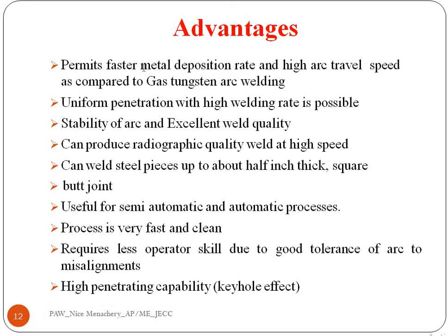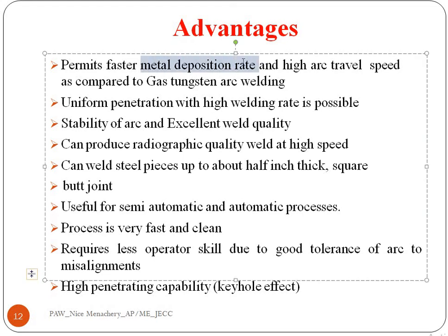And finally, some of the advantages of plasma arc welding are: metal deposition rate is very high, uniform penetration with a high welding rate is possible, stability of the arc, etc. The process is very fast and clean, less operator skill is necessary, and it has high penetration capability.